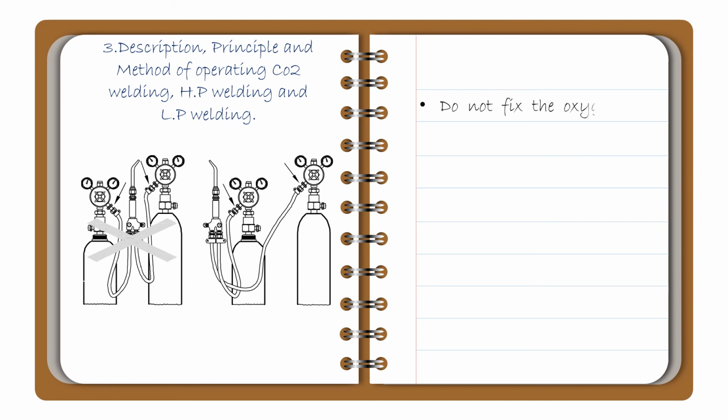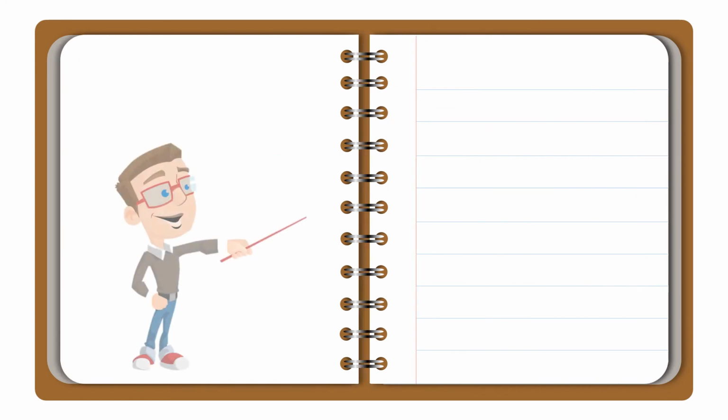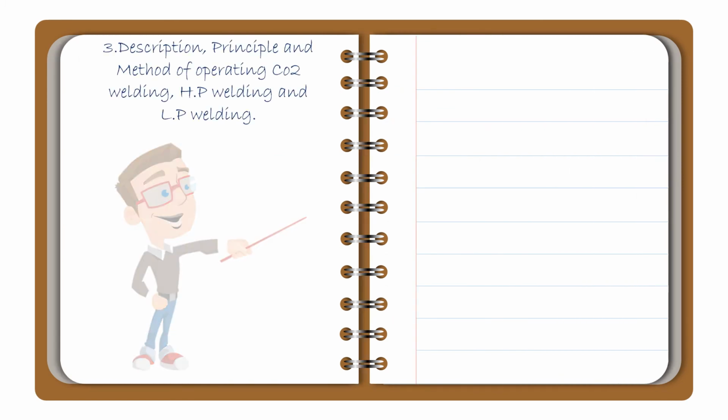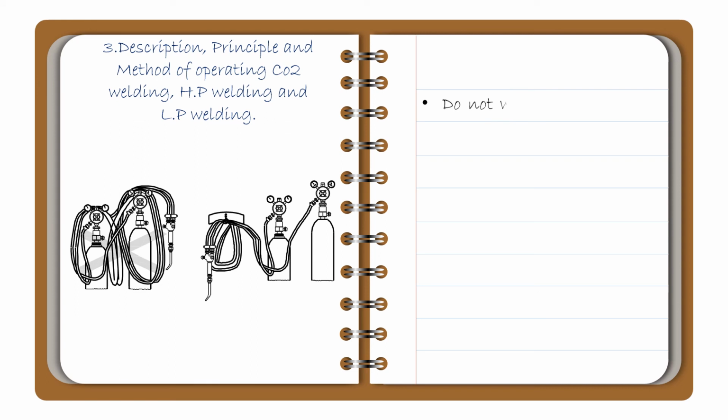3. Do not fix the oxygen and acetylene regulators close together. And 4. Do not wind the hose on the regulators.